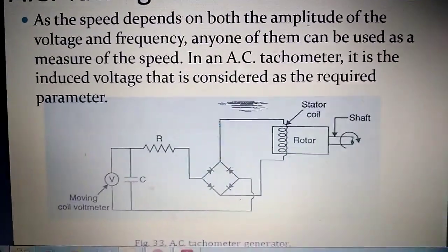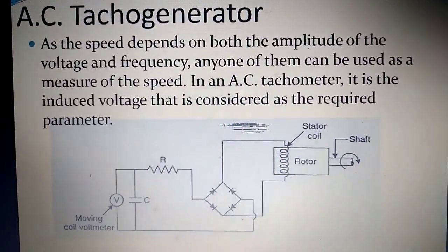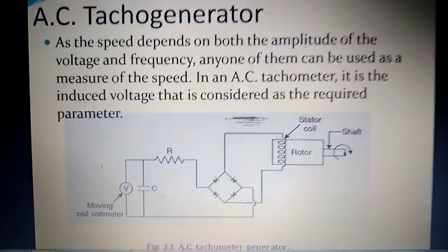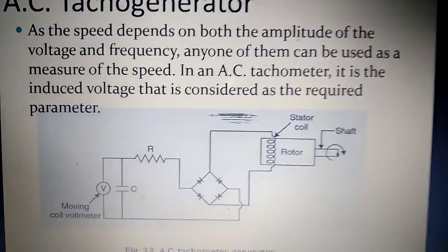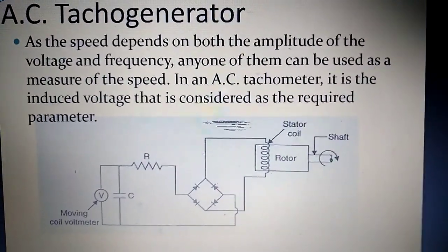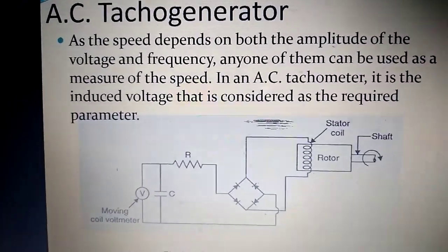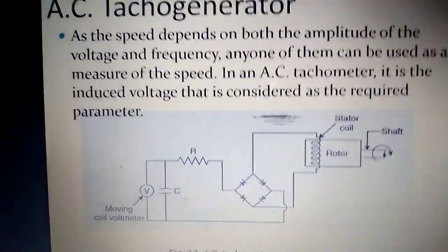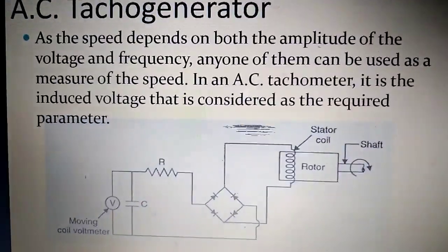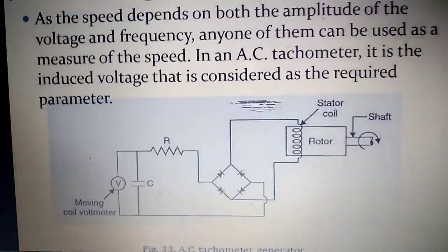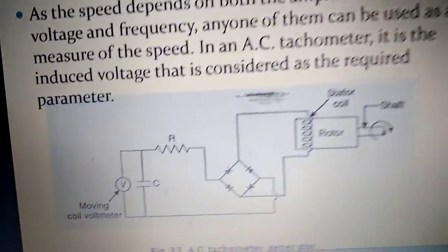The rotating shaft is attached to a magnet, because the magnet is attached to the rotating object, so the magnet also moves, which in turn generates a magnetic field. When the magnetic field strikes the aluminum coil, an electric signal is generated in the wire. So it gives a voltage that is directly proportional to the speed of the rotating shaft or machine.